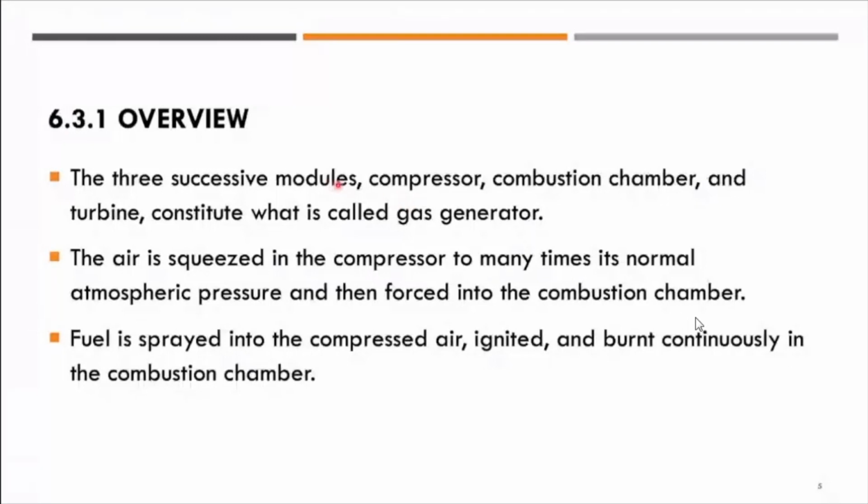When air goes into the compressor, it is compressed and pressure builds up, and before the flow goes into the combustion chamber, and then finally goes into the turbine, these constitute what is called the gas generator.